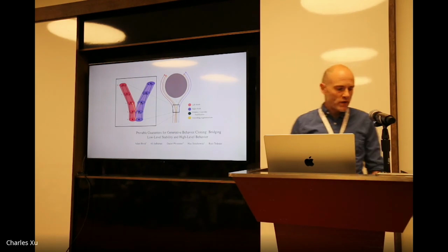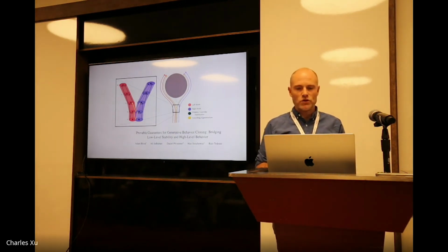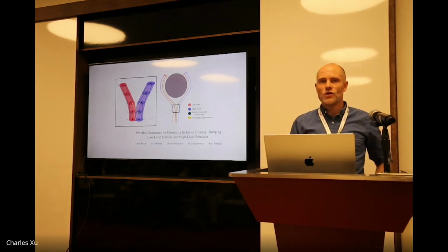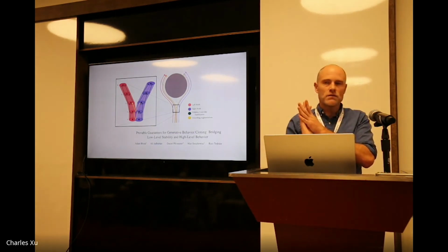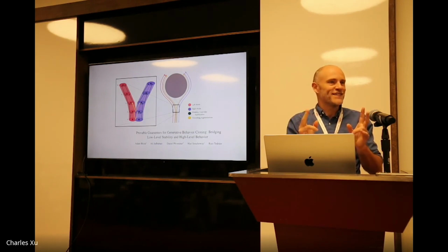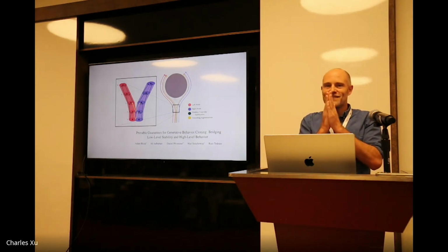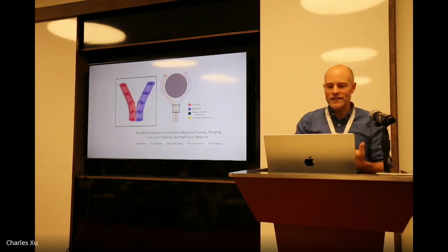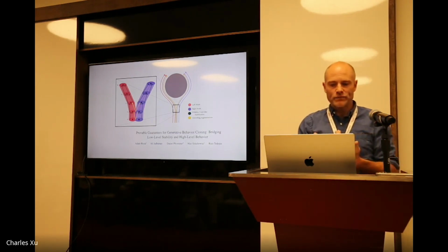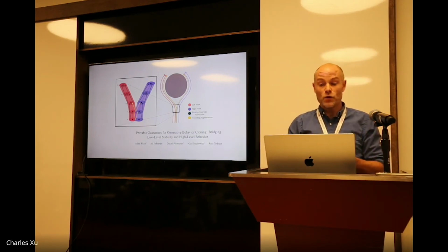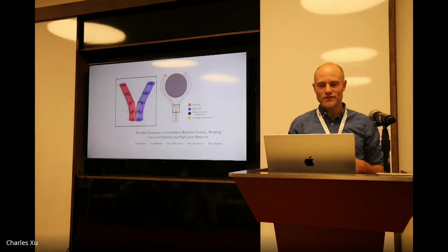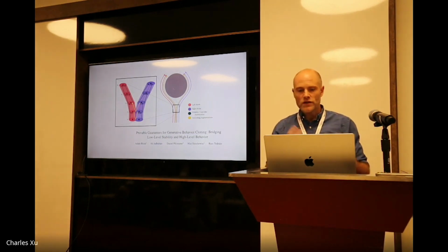So, I say it's good at handling multimodal demonstrations, but we also know that behavior cloning fundamentally wants stability, right? Because you don't want to walk away from your training data and get out of domain. So it's actually interesting. You would think that those are in tension, right? How can I be in the same state, possibly take different actions, but be stable? Those things feel like they should be in tension. But because it boils down to a simple model and we're seeing it through the lens of these forecasting models, you can understand that it is possible in these models to have funnels, if you like, that still go left or right around the obstacle. That's a very simple picture, but I think there's clarity that can be obtained by thinking these ways.